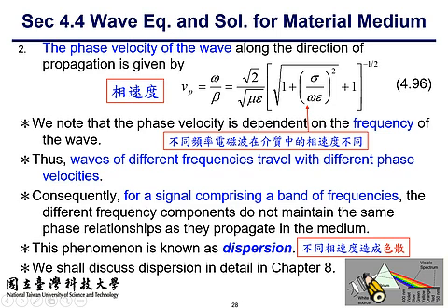And another important consequence associated with dispersion is on signal propagation in communication systems. For example, we know that a square wave can be decomposed into f sub 0 plus a set of F1, F3, the 3 times higher order mode, and then 5, and so on. So we know that using the cosine series, you can represent a square wave as the superposition of a cosine series.